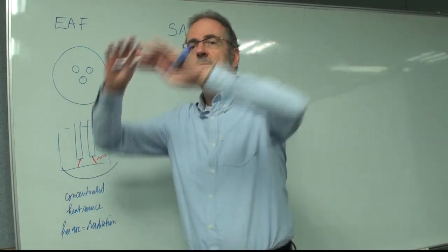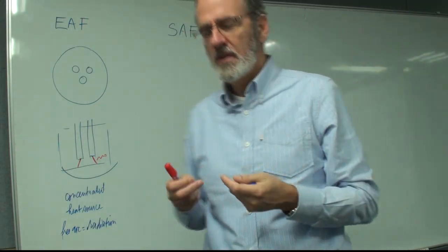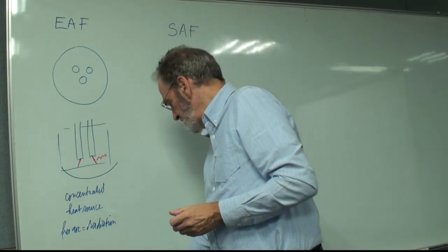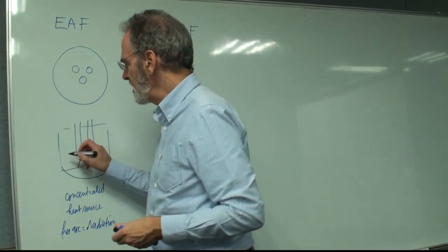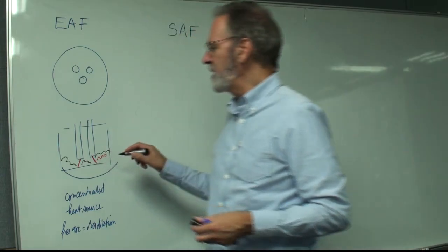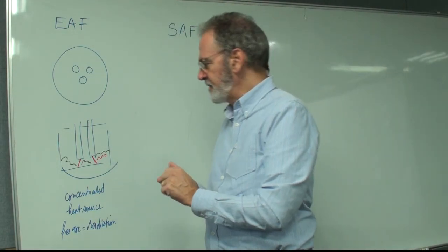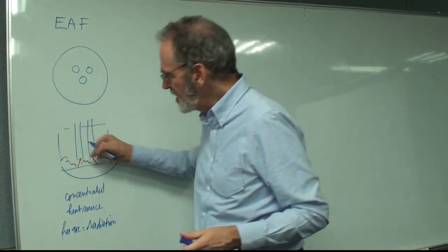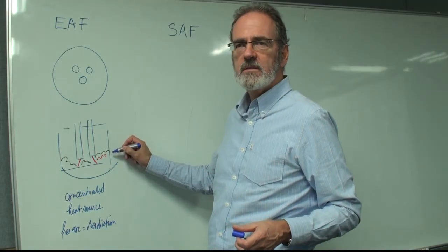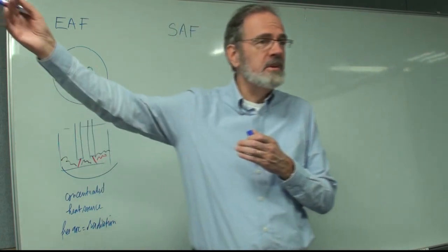It is very good because scrap is around the arcs and scrap takes all the heat. But when we have no more scrap, we have only some slag. Then it is good that the arcs are in the center, so that they don't radiate too much on the panels, on the walls. It's good to have the maximum distance.